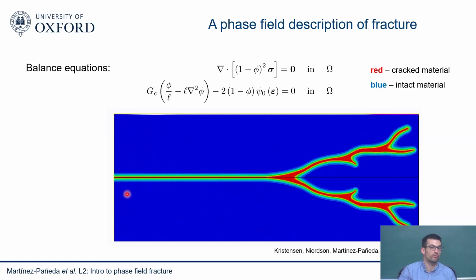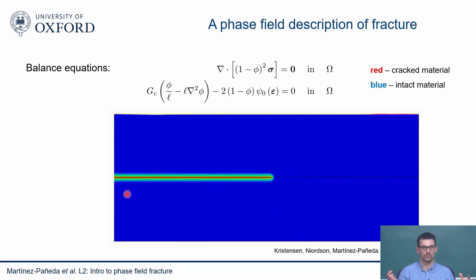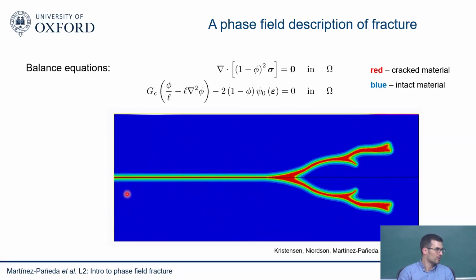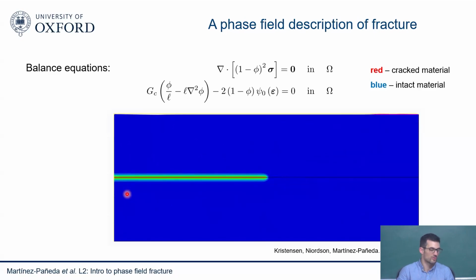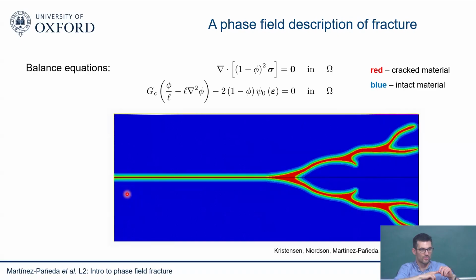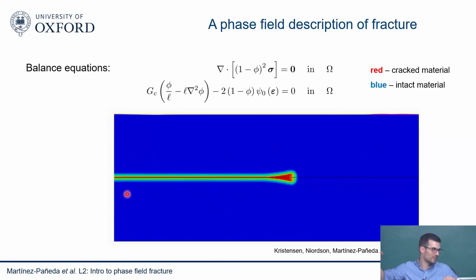And of any other fracture problem or damage model that relies on a fracture process zone, which are the only physically based ones, because you need to resolve the fracture process zone. So if you are trying to simulate something that is gigantic and you have a tiny fracture process zone and you don't know where your crack is going to go and you want to model the propagation of the crack for the entire dam, then that's going to come at a cost.